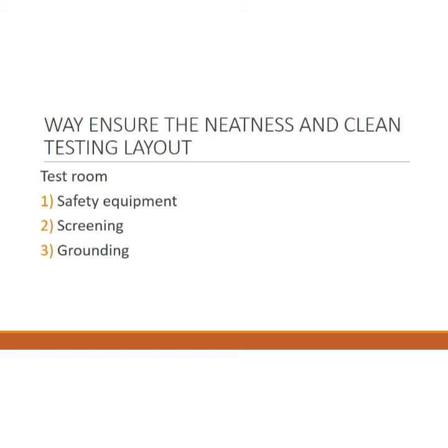The test transformer of a high voltage construction kit can be used for partial discharge measurement. In order to ensure the partial discharge measurement is not disturbed by external interference, it is necessary that the test room is screened like a Faraday cage. Walls, ceiling, and the floor of the test area have to be covered with a metallic surface.